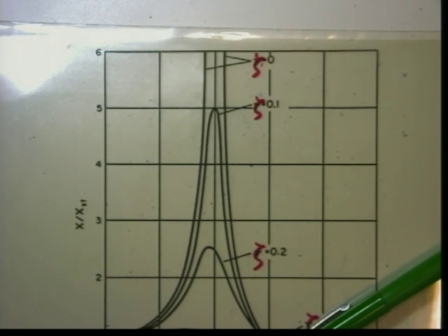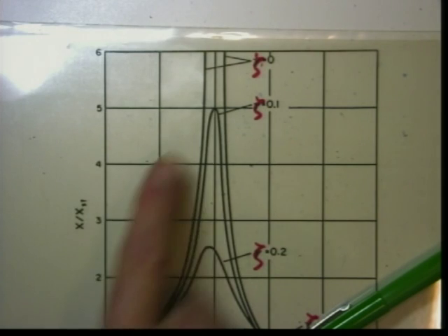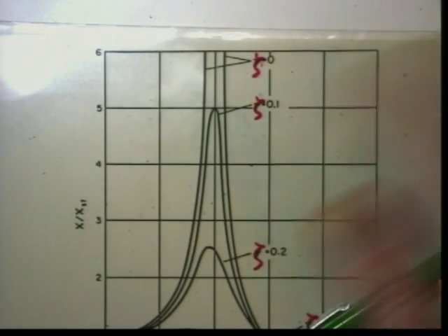But now, if there is damping, then the solution does not go to infinity, but still it could be very large. Therefore, resonance is not just an artifact of idealization, meaning I just did not take into account damping. It is actually a physical phenomenon. Without damping, the solution goes to infinity. With damping, it does not go to infinity, it goes to a large value. Look here, in this case the maximum equals 5, then 6, or something more.